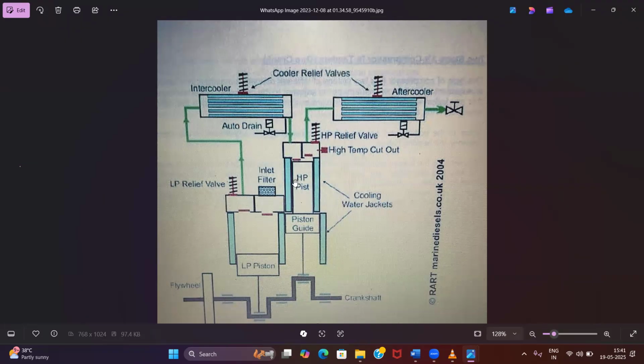Yes sir. Now you don't understand one thing. Is your water compressible? No, sir. Can water be compressed? Or can any liquid be compressed? No, sir. So as soon as the leakage happens, what is going to happen to the pressure? It may increase. It is going to increase and the bursting disc is going to burst.